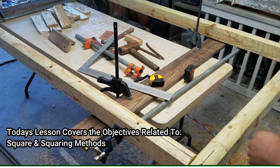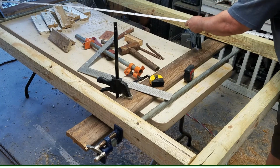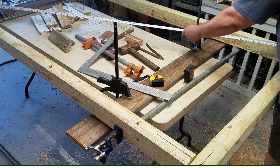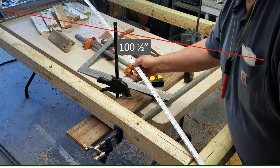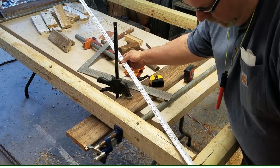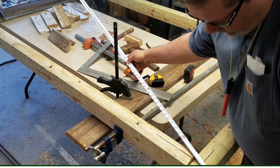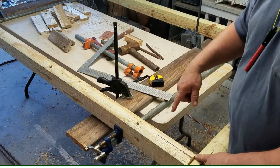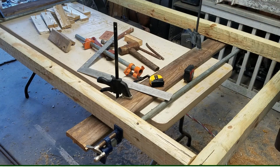All right, we want to check this thing for square. So we're going to measure from corner to corner. This corner says I got 100 and almost a half inches. Let's check this side. See, this long tape, this wide tape works good. Right here, I got 98, right at 99 inches. So what's that telling me? This is 99. This was 100 and a half. From this corner to that corner is an inch and a half bigger.